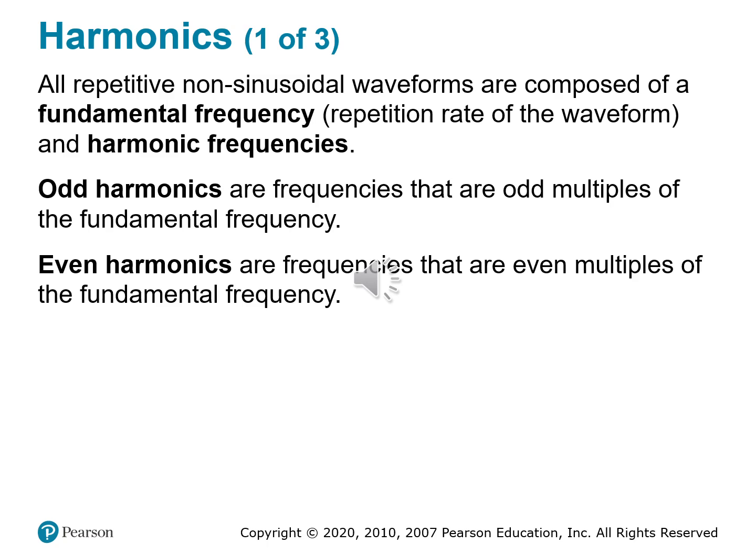But now when we enter harmonics, we have odd harmonics and even harmonics. Odd harmonics are the sine waves at 3 times, 5 times, 7 times that fundamental frequency. So square waves, for example, contain only odd harmonics. Even harmonics are like 2 times or 4 times or 6 times that fundamental frequency. These are found in asymmetrical waveforms like certain sawtooth signals.